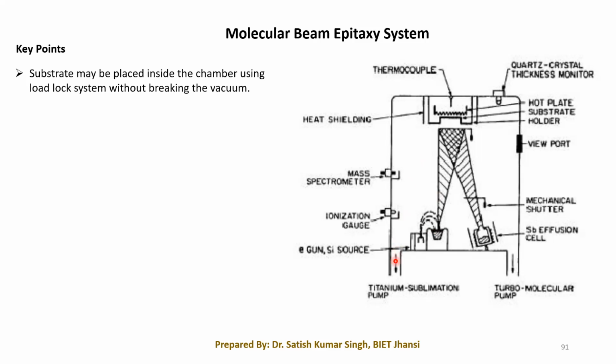You can see here we have two pumps: a titanium sublimation pump and a turbomolecular pump. This we have to achieve first. Before starting any process, we have to evacuate the chamber and achieve the ultra high vacuum, because molecular beam epitaxy will take place within the ultra high vacuum. Otherwise, other gases will be present and contaminate this particular wafer surface.